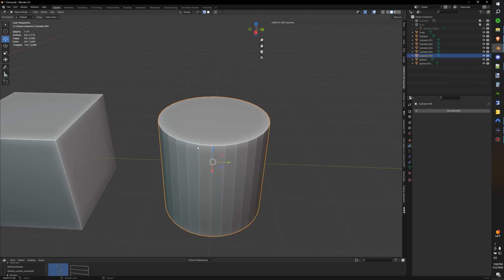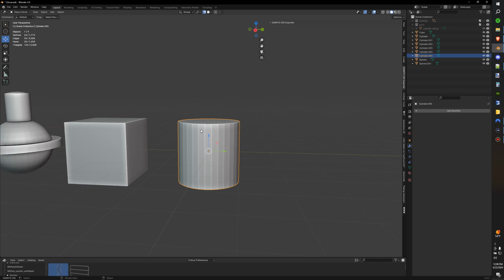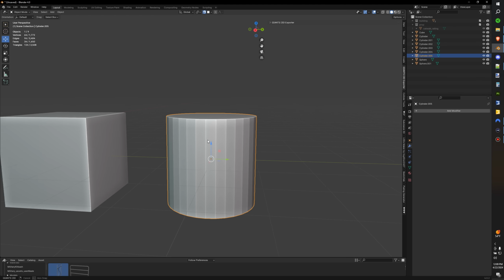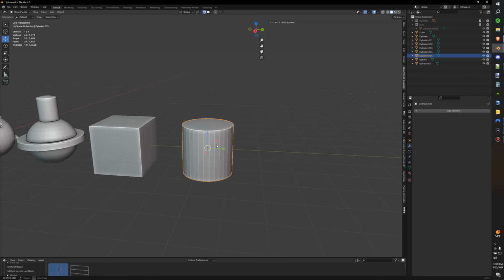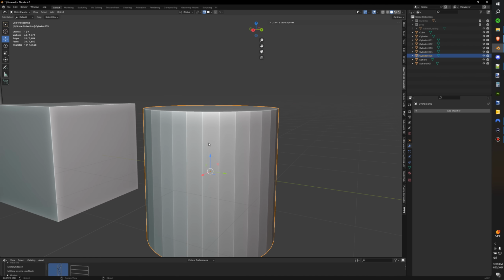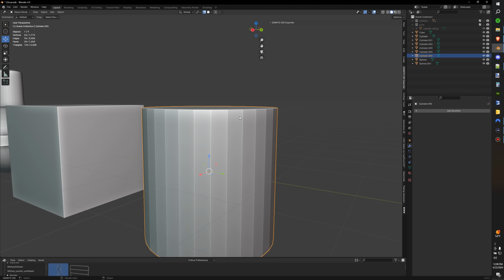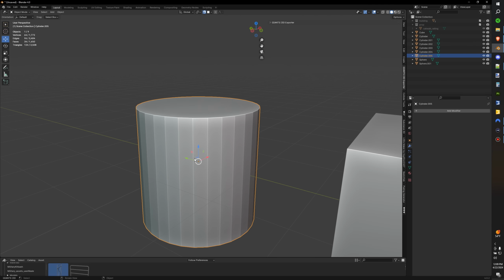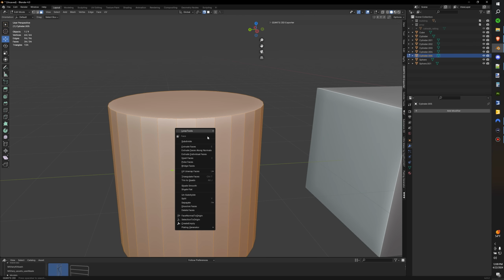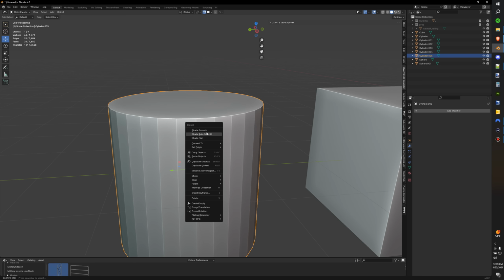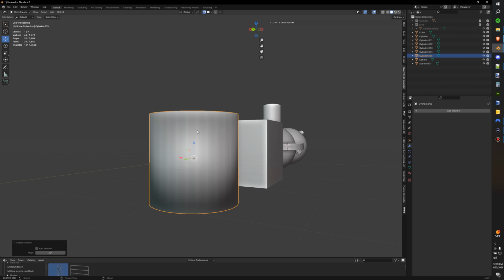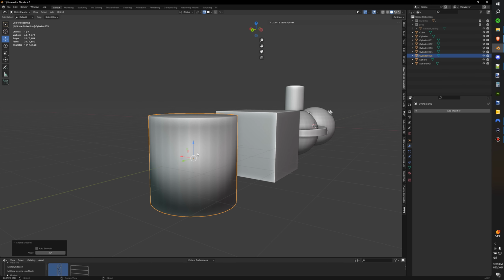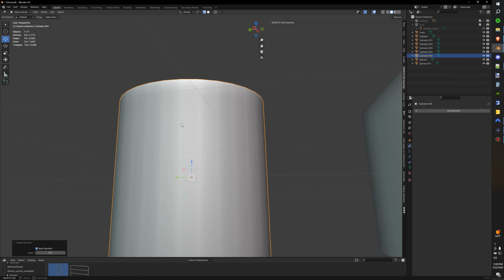And then when we look at cylinders, I struggled from this issue a lot when I first started modeling. Essentially, I would pull in some poles into Giants Editor, and I would see all these lines, and it just looks terrible. It doesn't look like a pole, right? So let's first see what shade smooth looks like. It looks horrible. It does the sides perfectly, but the tops should be flat. So if we go to auto smooth, it looks how it's supposed to look.